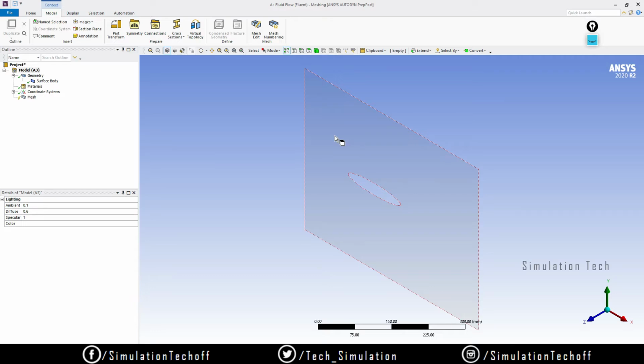This CFD solver uses an iterative solver. Iterative means it solves the problem by iterations, n number of iterations, like 10 iterations, 20 iterations. If your problem needs to converge, you should have a good, proper mesh. We will clearly explain what the iterative process is when we get into the Fluent model.